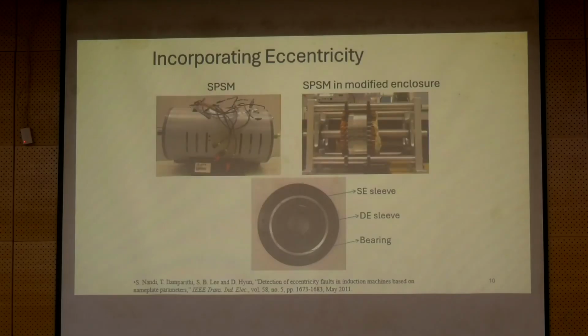So one thing I want to caution you is that all this setup, like this arrangement with bushings, will work out well if you do not have a permanent magnet in your rotor. So if you are planning to use a modern EV motor, which is permanent magnet based, and most of these permanent magnets are rare earth magnets, they're extremely powerful. What does that mean? You cannot pull it out or push it in as per your liking. So this approach of having eccentric bushings which can be replaced is not going to work out for modern